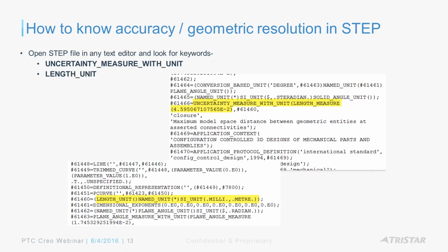right? The geometry resolution or accuracy, right? As you know, in Creo, when you import, you can either use the internal accuracy of your start part, that you guys have set up as a CAD admin. You guys have your own stock parts that you use with your own accuracy, or are you going to be using the external accuracy of the imported geometry?